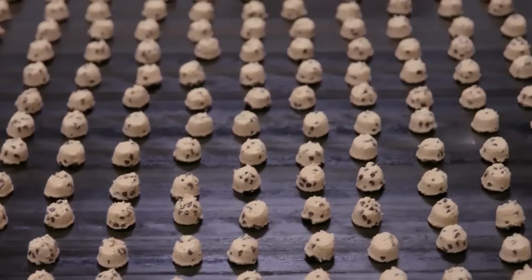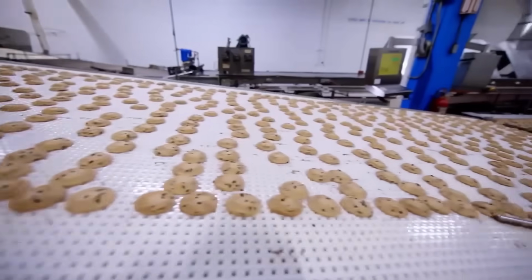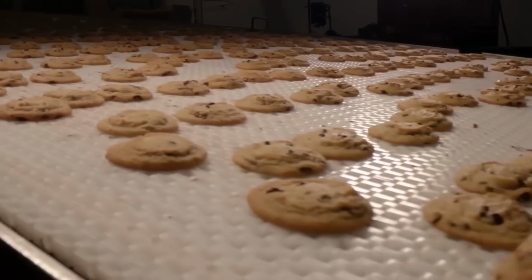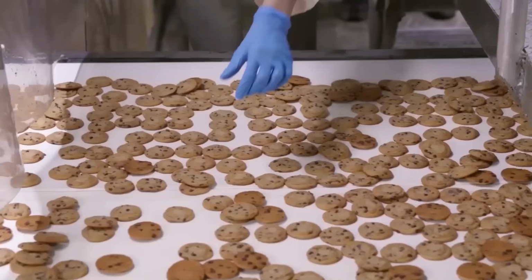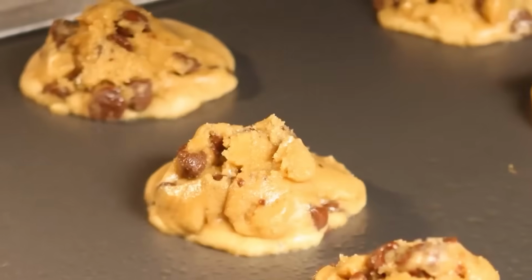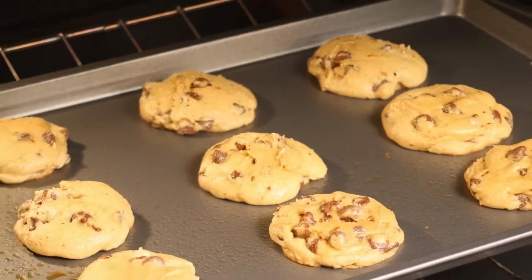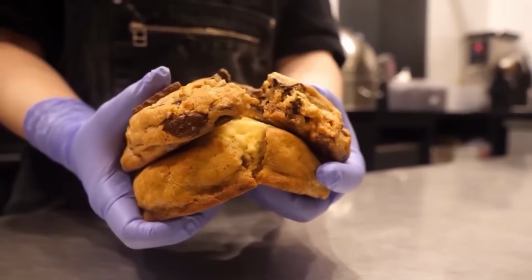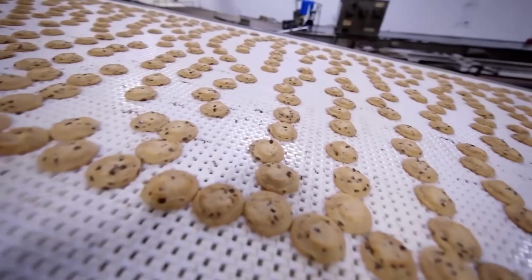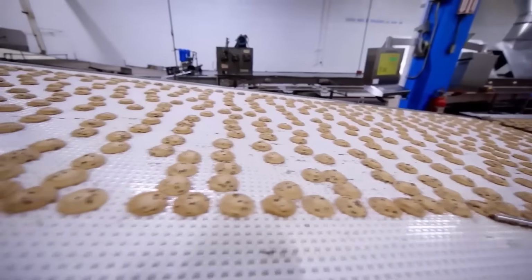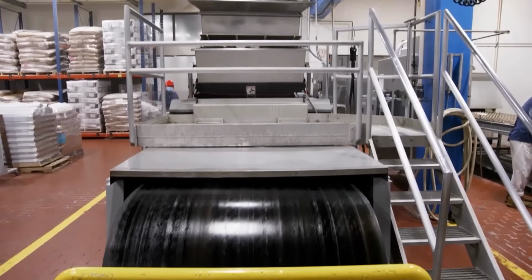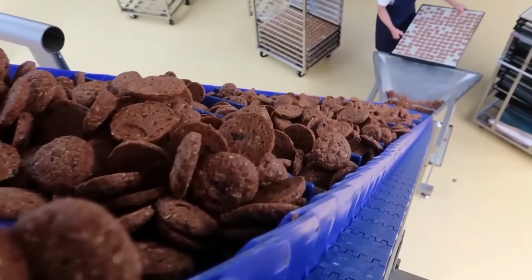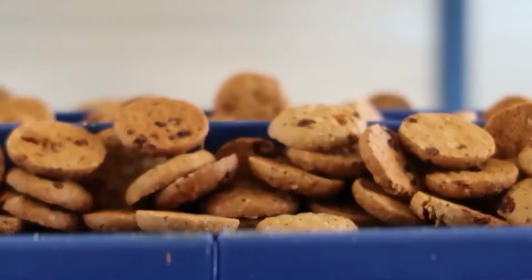Each pallet is scanned for completeness, using weight and barcode validation before being stretch wrapped in polyethylene film at 250% pre-stretch. Wrapped pallets are moved to finished goods warehouses with controlled temperature and humidity, typically 18 to 20 C and 50 to 60% RH. Every stage of the process is controlled and logged using a manufacturing execution system, MES.